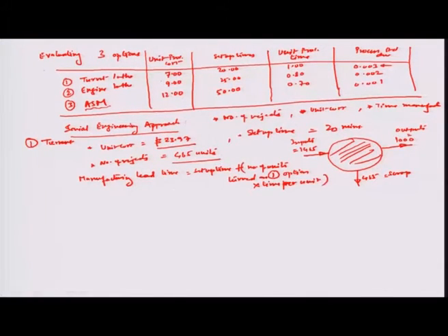So this is about 20 plus 1465 times 1.00 time units, which is about 1485 time units or minutes. So the serial engineering approach produces with the turret lathe a product which has a unit price of about $23.97, rejects about 465 units and takes a manufacturing lead time of 1485 units, and this is the alternative which was chosen in the serial engineering approach.